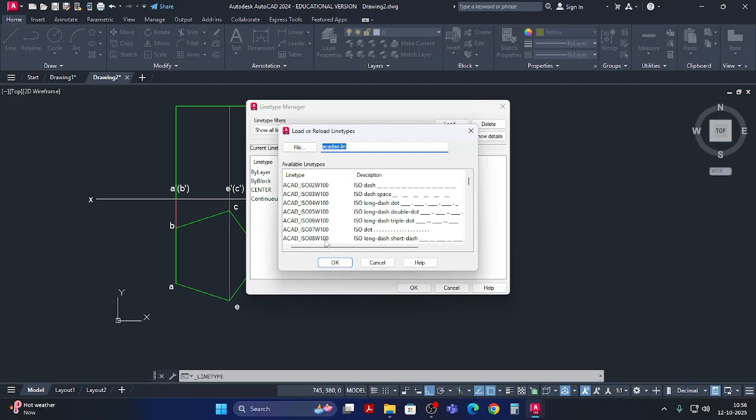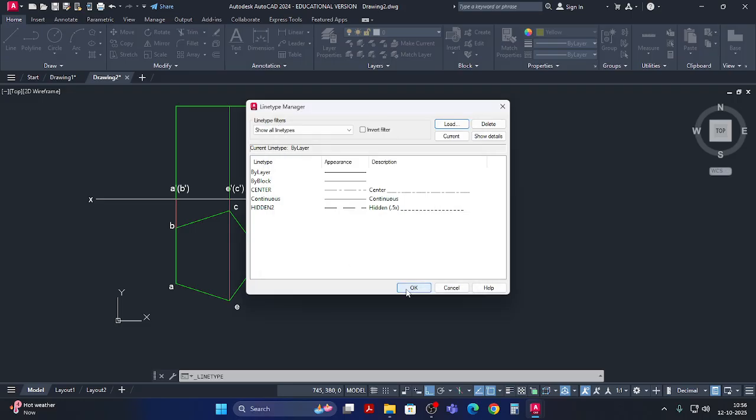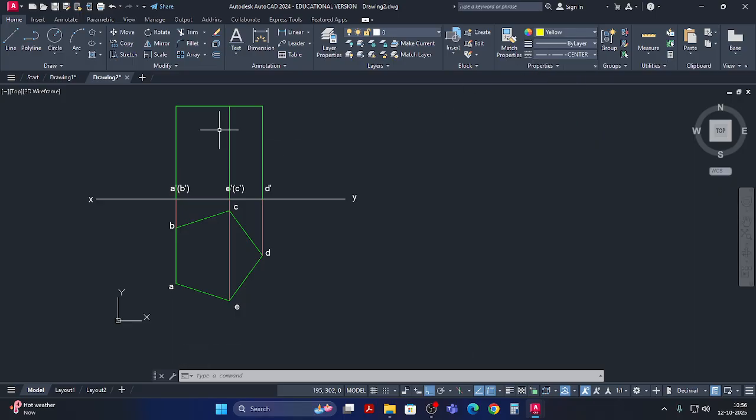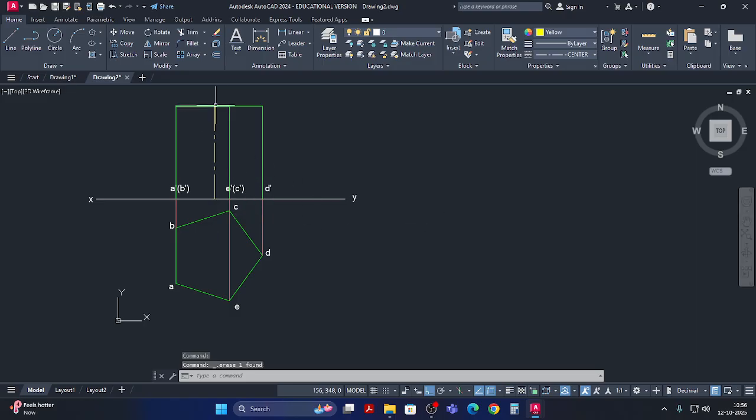Along with that, hidden lines also can be customized. H for hidden. You select OK. Okay, then two lines can be customized here. Okay, so you take center line with the yellow color and draw a line on this middle. You select this as a reference. This will be the solid middle. Okay, top view. You project it here to here, one center line. Thereafter you delete this line because we need only this length of axis line.